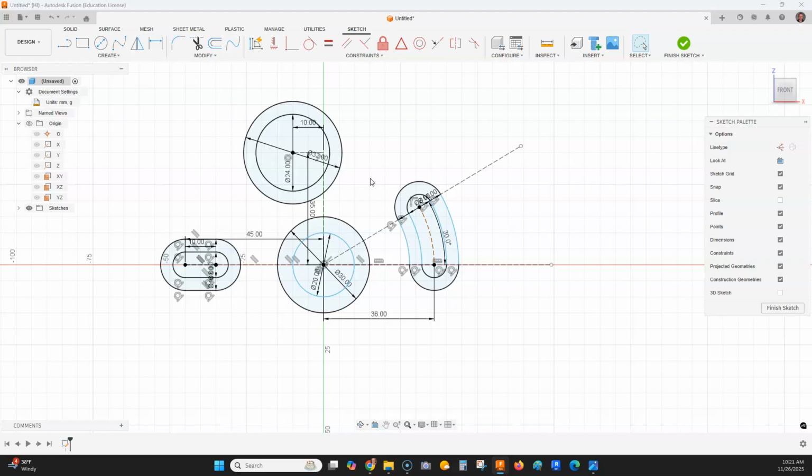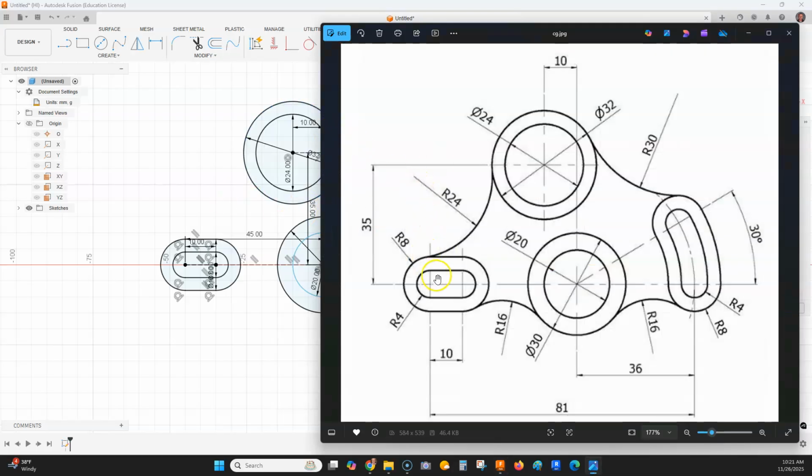So we now have the geometry that might make a little bit more sense to you as you took a look at it. Like I know what an arc is, I know what this is, but what are these things? These are tangent arcs, and there's more than one way to create these, and I personally have a way I like to do these that guarantees tangency. I like to do circles and then use the tangent geometric constraint feature myself.